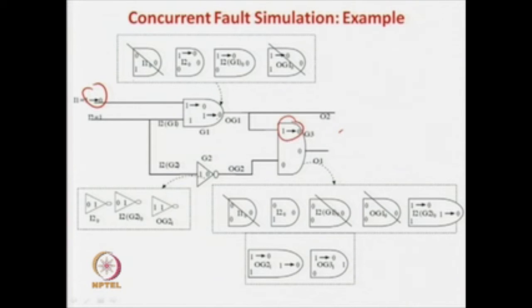So in this case this will be the change from 1 to 0, and now you can see that this corresponds to this net stuck at 0. So this whole list is from the old computation. So now you can see that because of this change, the normal condition will be 0 0, and the answer is a 0. So this is about this gate.